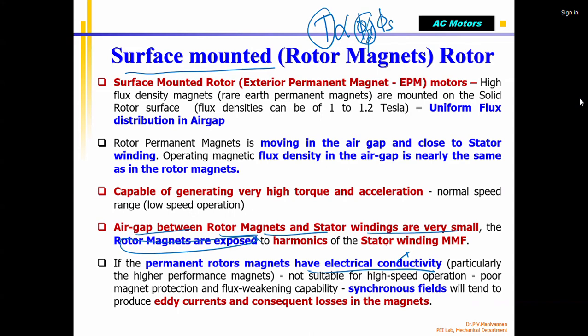And another thing, the electrical losses, or magnetic power loss, created in the permanent magnet is directly related to the RPM of the rotor. If the motor rotates at higher speed, more magnetic flux will be cut by the rotor magnets, more eddy current, more heat. The permanent magnet will lose its magnetic flux quickly. Then the torque produced by your motor will drop. After a few years, you give a warranty for your vehicle, correct? With a permanent magnet based surface mounted rotor, you are using a 100 kilowatt motor, for example, 200 Newton meter torque. Okay, you said the 5-year warranty, correct?